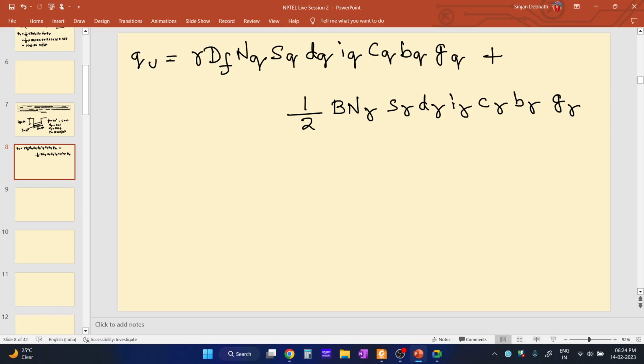There is no need to incorporate this sloping ground factor because there is no slope, only tilt. So only bq will be there, and only the b term will be there. Over here also only the b term will be there. This will not be there. Soil compressibility has been asked over here not to be considered. So that means cq and c gamma will also not be there.